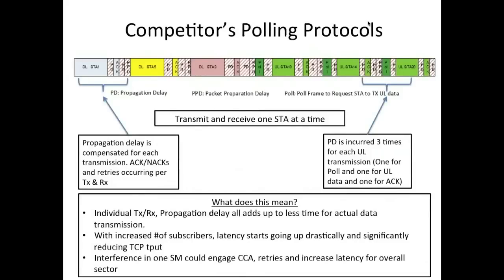A little bit deeper technical background on this MAC concept we talk about. The message here that I spoke about, where we said that 20 to 30 subscribers in a system starts degrading, really has to go back to what is known commonly as a polling protocol in a lot of systems out there. Polling protocols are fine to some extent, but when you try to add a lot of CPEs to an access point, polling protocols do fall apart to some degree.